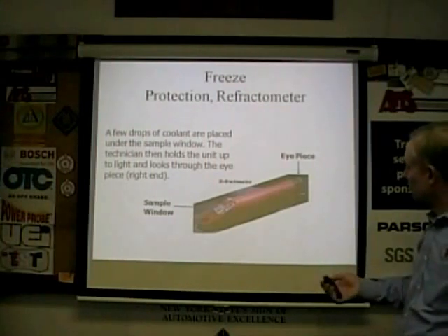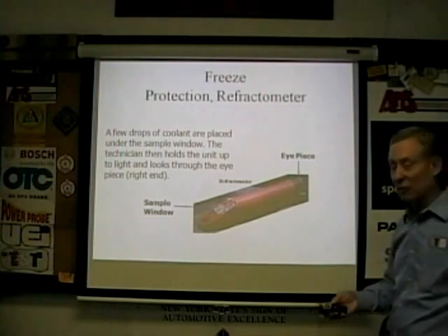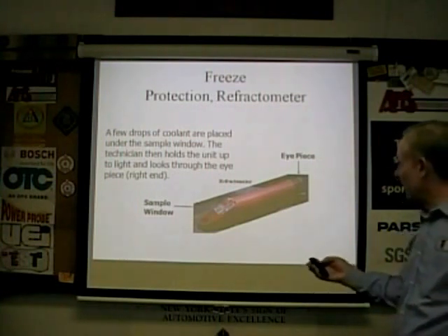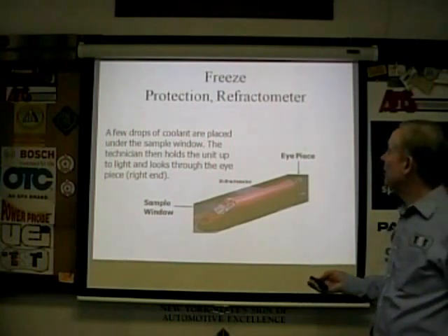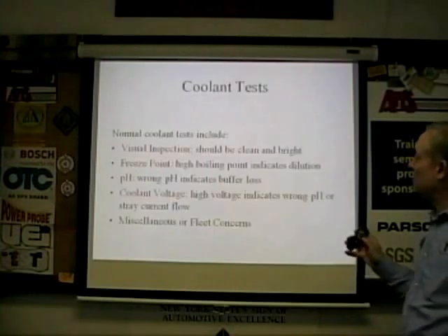One of my favorite tools, a refractometer for testing your coolant or actually your acid protection for a battery. Very accurate, maintains its accuracy. Way better to use than those ball things, that's for sure. Better than a hydrometer, much better than a hydrometer.